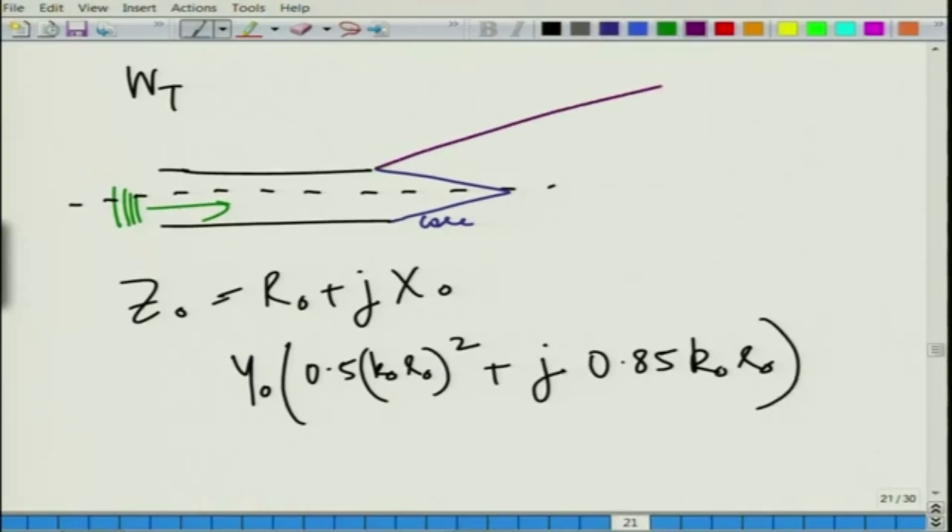There is a shear layer in which the rapid mixing of the jet happens. Although by the time it comes it is not a supersonic jet, it is pretty much a subsonic jet, you still would have a potential core and a top hat profile, which gradually becomes a Gaussian profile downstream. So, this is the mixing region really, or the shear layer as we say.